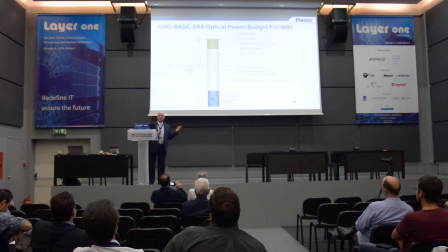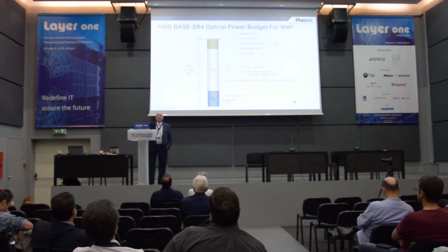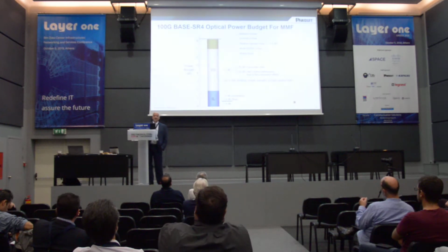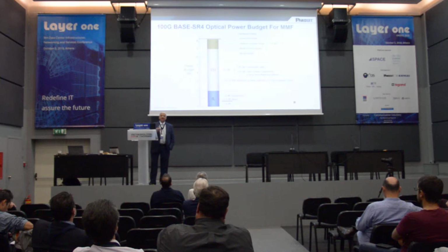And again, you don't have control over it directly, but the way you do have some control over it is selecting the type of multimode fiber that you use. I'm going to describe what intersymbol interference is, and that's where we get technical. So intersymbol interference is the primary penalty that's going to limit a channel from 50 gigs and beyond. Insertion loss is, I hate to say it, actually not important, as an example.